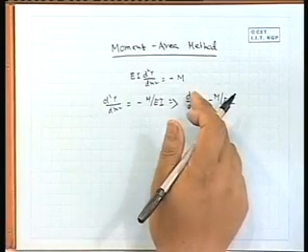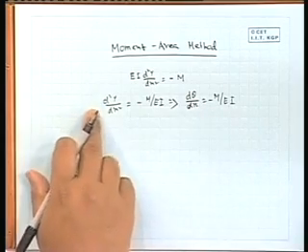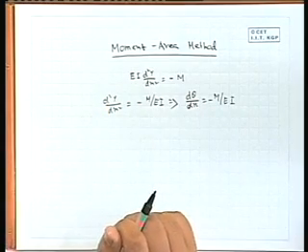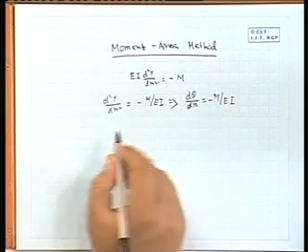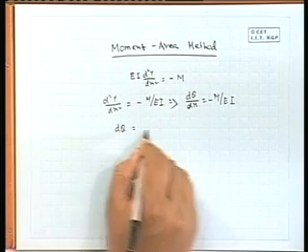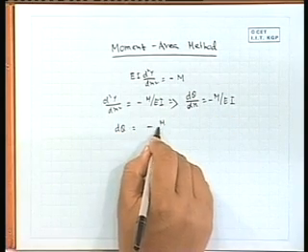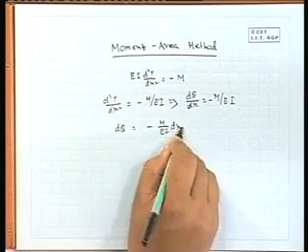So, if we put theta equal to dy by dx, we are supposed to get d2y by dx square, right. Now, this is one equation. So, d theta will be your M by EI dx, right.